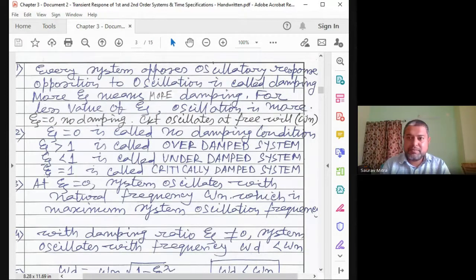It's an LC system, and you will be studying the LC oscillator. There are different types of oscillators. A crystal oscillator is there in every system, a piezoelectric crystal that oscillates and generates some kind of frequency. But in the initial days there was no crystal oscillator, there was only the LC type of oscillator. Inductor and capacitor, when they are in parallel, with no resistance, in an RLC circuit with no resistance, together produce something called a tank circuit.